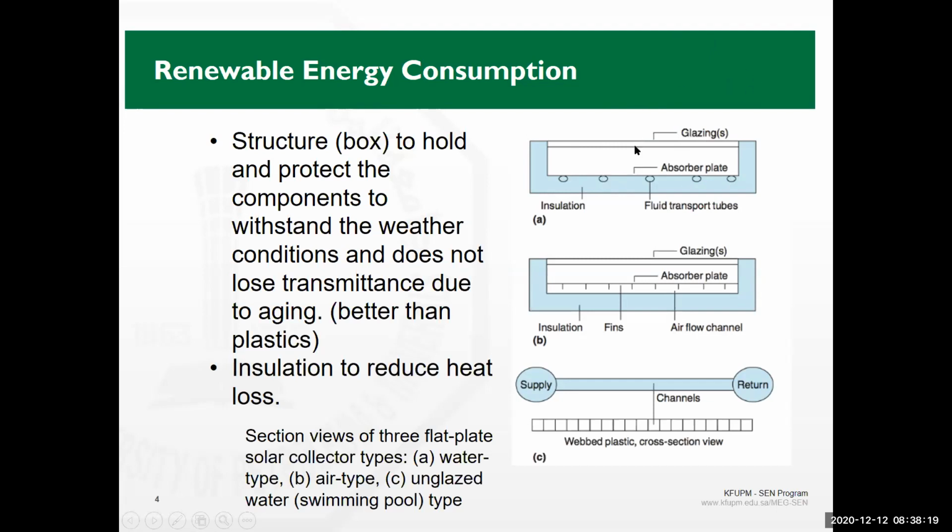Whatever will penetrate through the glass has radiation surface properties, which are absorptivity. It can absorb part of the energy. The glass itself gets heated. The major property is transmissivity. It transmits the solar energy through. The third property is the reflectivity, so it can reflect back some of the solar energy.